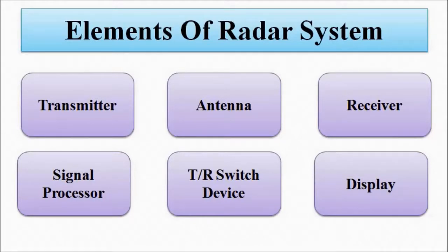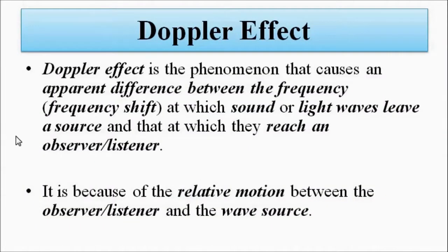So an important component of this whole measurement, which is the velocity measurement, which gives us information about the speed, the velocity of the target object, is processed with the utilization of the Doppler effect. It is based on frequency shift, the frequency change between the transmitted and the reflected or received echo signal. So before doing that, we should understand what the Doppler effect is and how it is utilized to get us information about the target velocity.